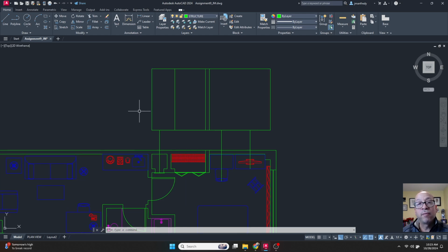So we have a file called the bedroom elevation file that's been provided, and we're going to use blocks inside of that file in our current project. And we do that using Design Center. So let me change this to 0 layer, and let's use Design Center to find blocks in another file and then bring them into this current file. So I can very quickly type Design Center.